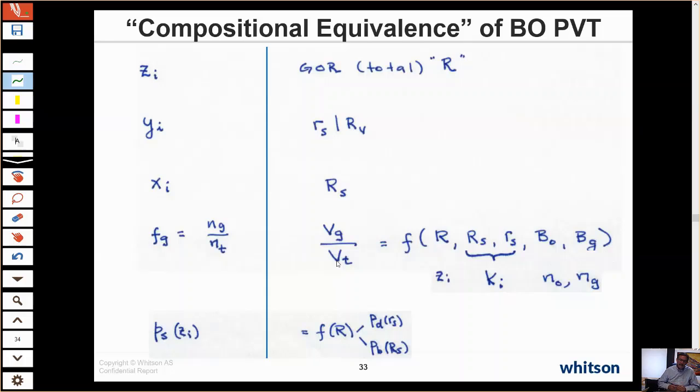The reason for that is because the gas oil ratio, which is what's kept track of in terms of the volume of stock tank barrels and the volume of standard cubic feet, kept track of in every grid cell from initially throughout the entire simulation run, is basically keeping track of 2 molar amounts of 2 components.